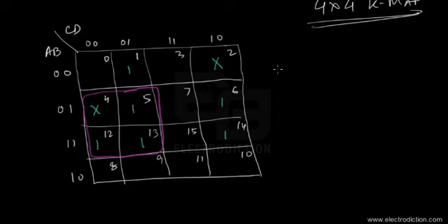We have 2 don't care elements over here. So if it appears that we can group them up together with the other valid elements that are present along with the don't care ones, so if we can group them up together to form a quad or a duplet, only then shall we use them up. So it's not a necessity that we have to use the don't care elements. It is nothing like that.